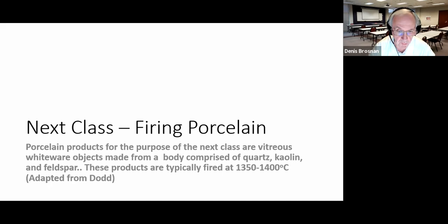So the next class, we're going to talk about porcelain. It's a more difficult product to make than heavy clay products. It's made by different processes. The bodies are typically composed of quartz, sand, brown sand called potash flint, kaolin clay. We use something to bind it together, and feldspar to create glass. And they're fired at higher temperatures, and you can see right away they're fired at temperatures that can change quartz into cristobalite. So that's going to be a neat class.